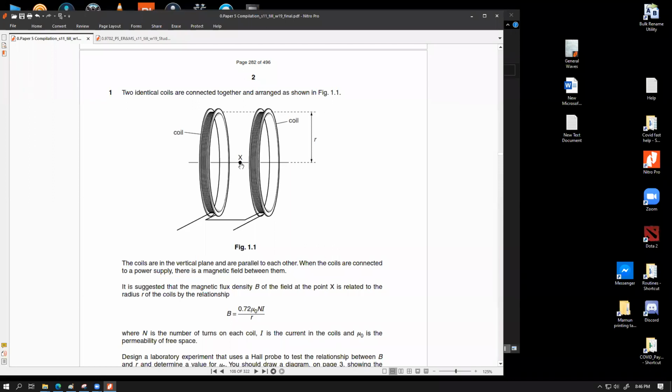For example, let's say you take a reading for 10 seconds, then you wait at least 5 minutes, and then you take the second set of readings for another 10 seconds. It's important because we don't want to heat up the coil and take messed up readings. Any time we flow current through an electrical circuit, it will heat up, and heating up can give you a different set of readings, which we don't want messing up our data.